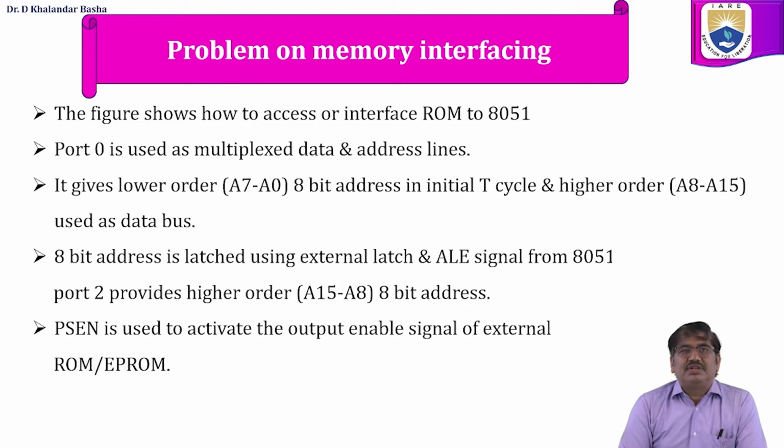The figure shows how to interface ROM to the 8051 microcontroller. Port 0 is used as multiplexed data and address lines. It gives the lower order address lines, that is A0 to A7, in the initial clock signal, and the higher order address lines, that is A8 to A15, are used as the address lines.